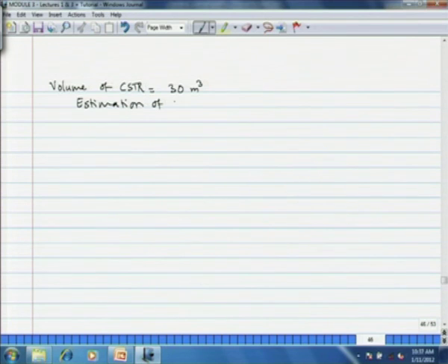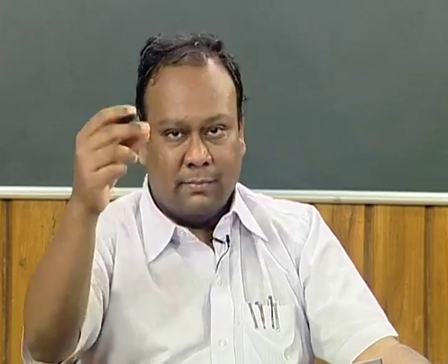Before we do that, we have to select the type of reactor and accessories. Since we are carrying out fermentation, we have to go either for a stainless steel reactor or a carbon steel reactor with some lining for prevention of erosion, let us say glass lined. Then it has to be a jacketed reactor to control the temperature, and it should have sufficient mechanical agitation. Okay. So, that point we note here.